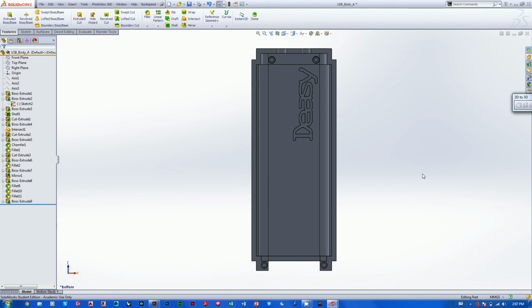A couple of things to just watch out for when you're importing that DXF file: number one, make sure your Illustrator file that you're building on is a similar size to the part that you're building on in SolidWorks. Make sure that the units of measure are the same across the board. If you're building in millimeters in SolidWorks, make sure you're building in millimeters in Illustrator. And don't forget to use sketch relationships to your advantage when orienting your part in 3D space.